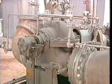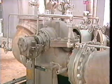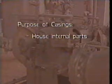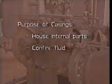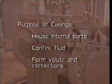Casings are usually made of cast iron for low-pressure pumps and of steel for high-pressure pumps. Steel or cast iron casings serve 3 primary purposes. They house the internal parts, keeping them in the proper position and protecting them as well. They confine the fluid being pumped and direct its flow. And finally, they form the volute and connection points for suction and discharge piping.